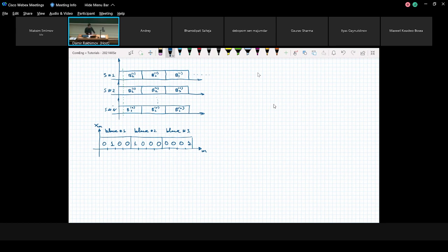What usually you do when you calculate autocorrelation, take your sequence, you make a copy of your sequence. And then you start shifting one copy relative to another one. Every time you calculate the element-wise product and calculate the overlapping area between these two sequences. And here we do the same, but surprisingly, our autocorrelation depends not only on the value of shift between sequences, but it also depends on the place where you start measuring this autocorrelation, for which point you calculate autocorrelation.